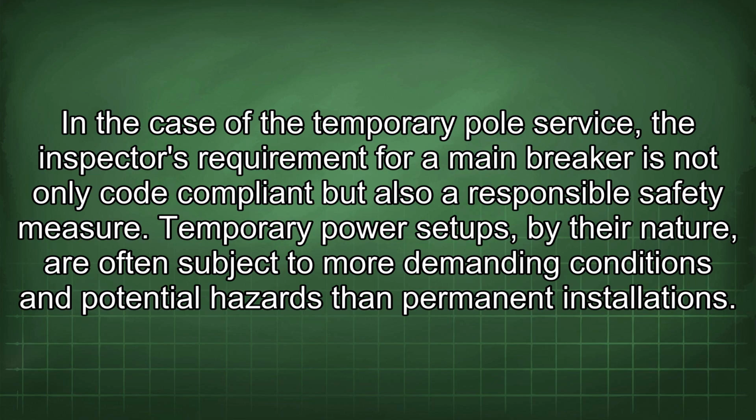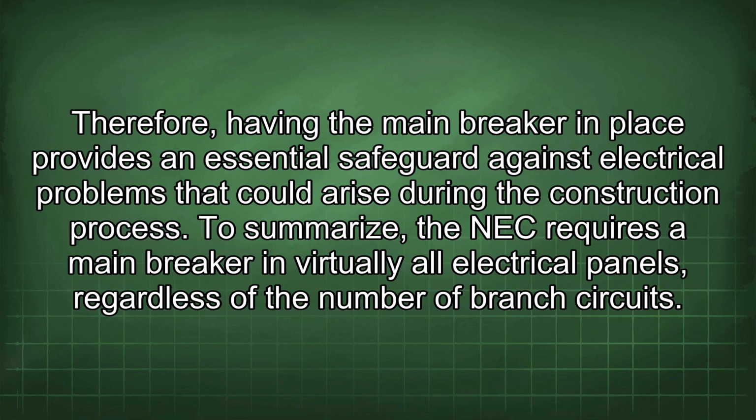In the case of the temporary pull service, the inspector's requirement for a main breaker is not only code compliant but also a responsible safety measure. Temporary power setups, by their nature, are often subject to more demanding conditions and potential hazards than permanent installations. Therefore, having the main breaker in place provides an essential safeguard against electrical problems that could arise during the construction